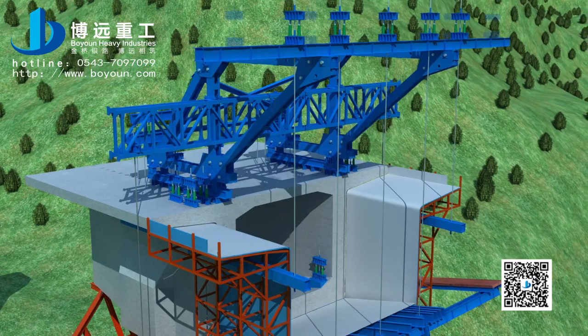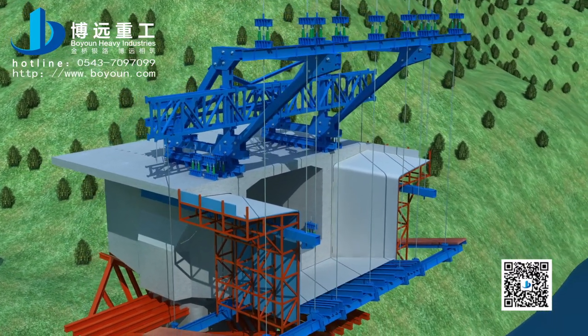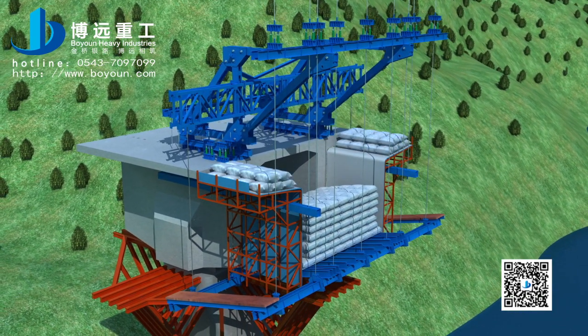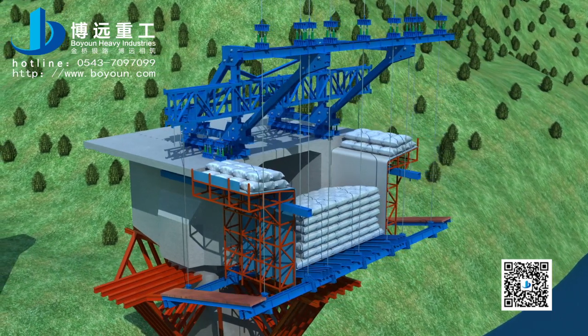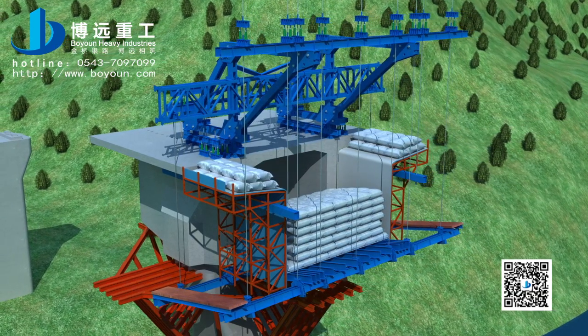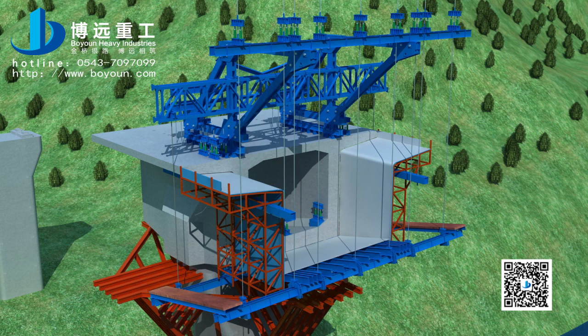Review the drawings and adjust various parts of forming traveler again to designed place. Pre-press the hanging basket structure according to pre-press scheme. Compare the pre-press monitoring data with Midas modeling model stress data and keep them consistent. Adjust the bottom elevation of forming traveler.